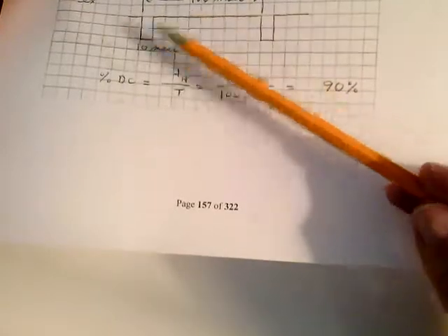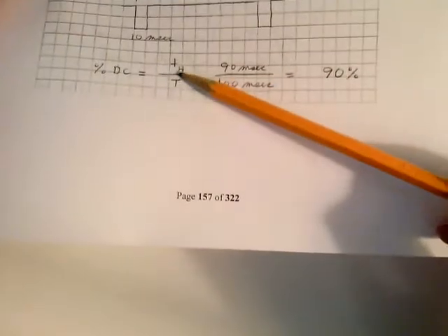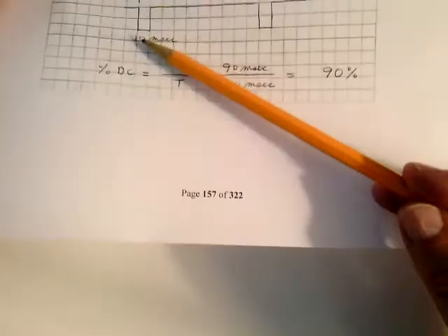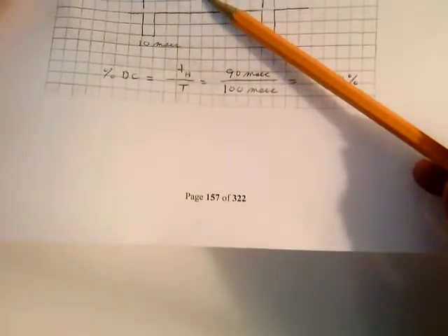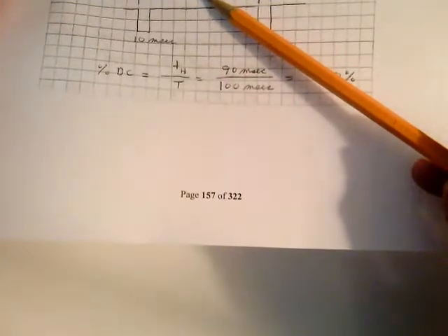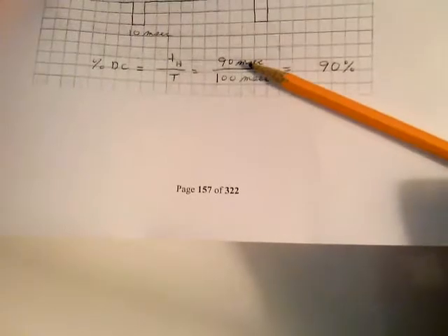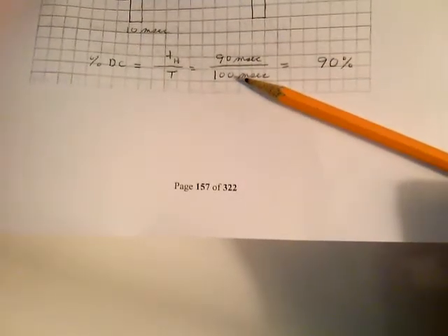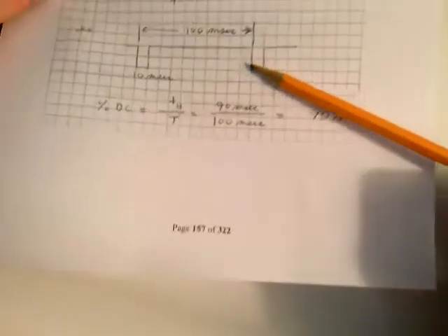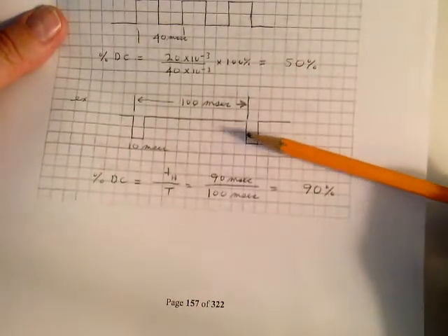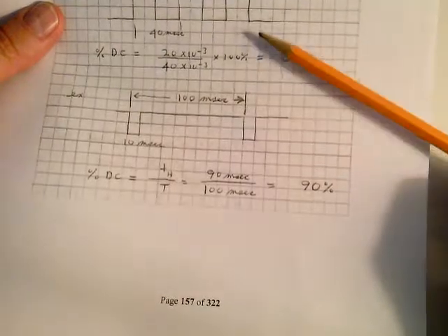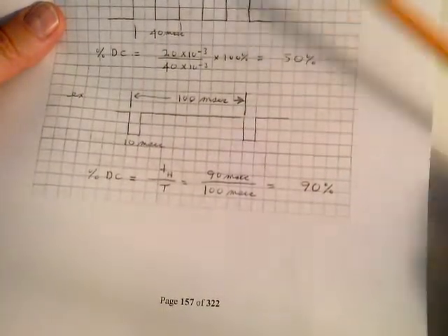Next example. Same thing here, except it's negative going clocks. Notice that the time high is a lot longer than the time low, but it's still T high divided by the total period. If it's low 10 milliseconds, and the total period's 100 milliseconds, that's 90 milliseconds high divided by 100 milliseconds times 100%, that's 90%. That's what a 90% duty cycle looks like right here in that second example. That's a 90% duty cycle. This is what a 50% duty cycle looks like up above.